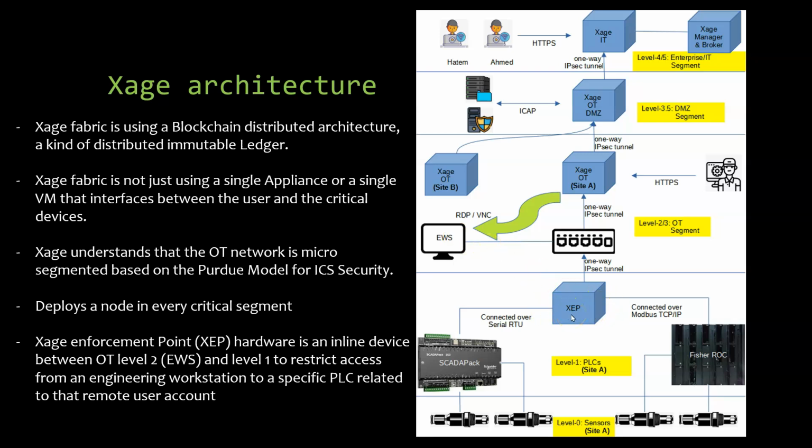The ZEPs, guys, are hardware that you purchase from Xage, as I said before, and it is positioned in line between the OT level 2 devices like the engineering workstations and the level 1 controllers, the PLCs, just to restrict the access from the engineering workstation to a specific PLC for that remote user account. So for example, Ahmed or Hatem, the vendor, has access to the engineering workstation.